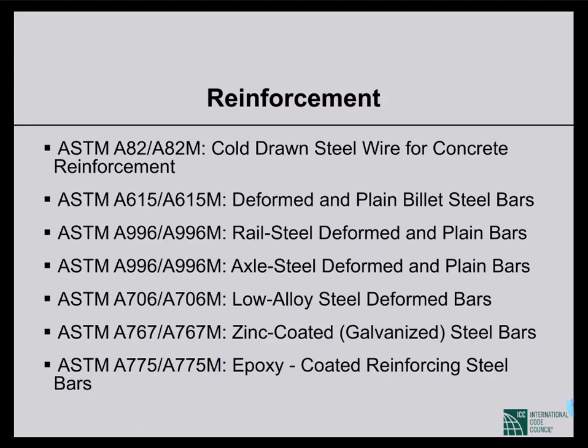Those are ASTM A706 type rebars. So we can use ASTM A706 or normal type ASTM A615. Wires are also available, 6mm or less diameter rebars. Wires are also available in our country, and epoxy coated rebar can also be used. So all types of rebars can be used as reinforcement.